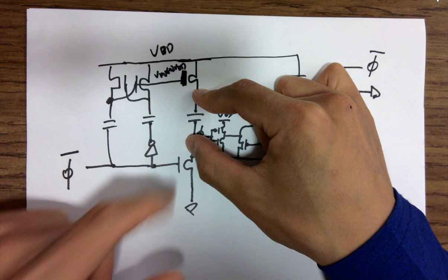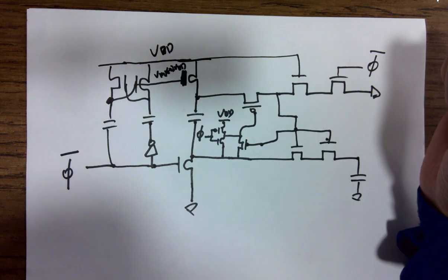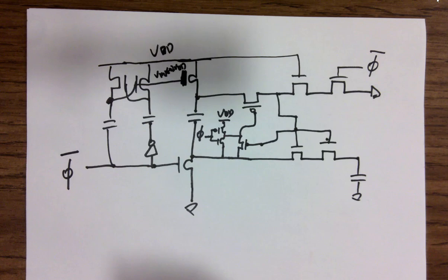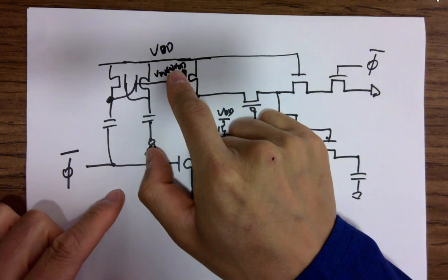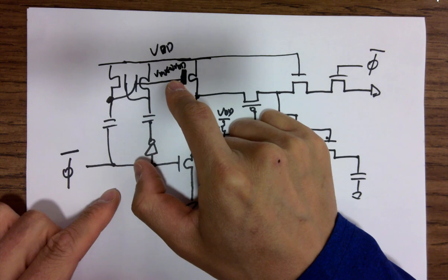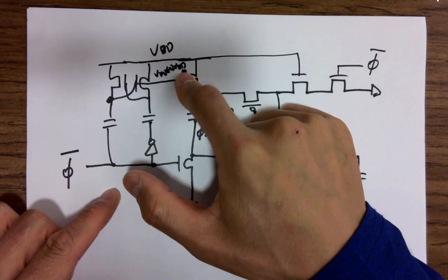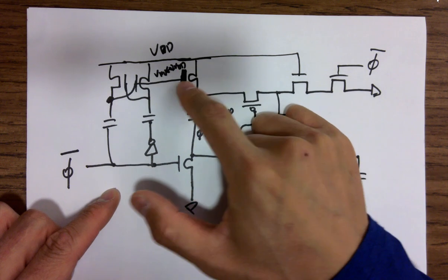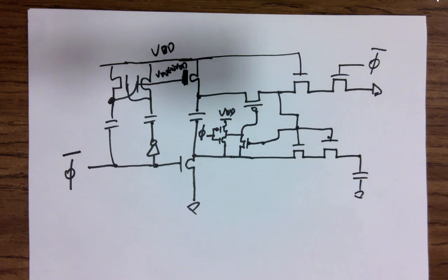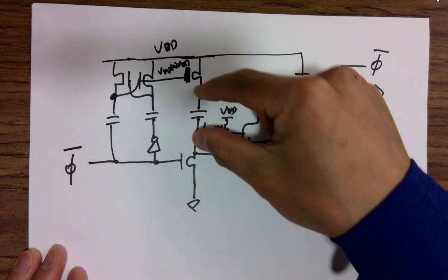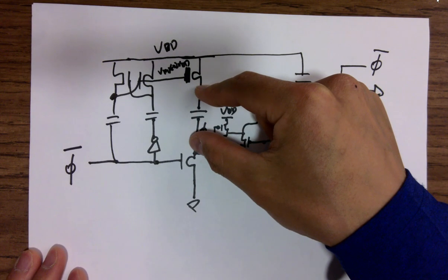And why? The gate voltage here is 2 VDD. Yeah. So 2 VDD minus VTH. How much you can store over here? This is widely open. It's larger than 1 VDD, right? So you should be able to pass the entire VDD over here. Right? Yeah. You should. Okay, that's the whole point. That's the whole point of using this charge pump, because we have a 2 VDD, so we can pass the entire VDD over here. So not minus VTH anymore.